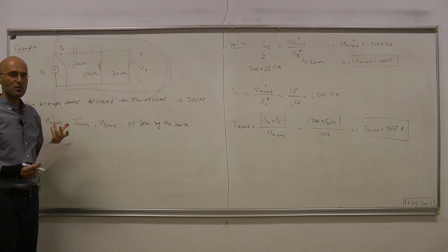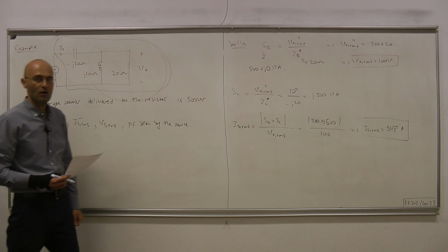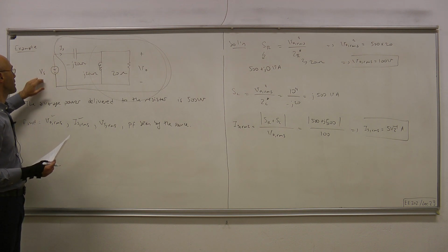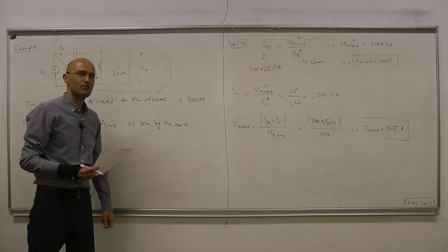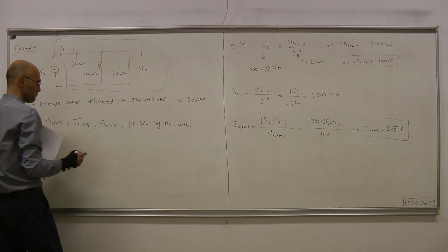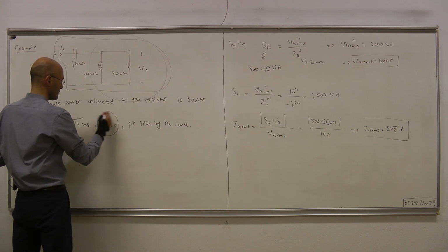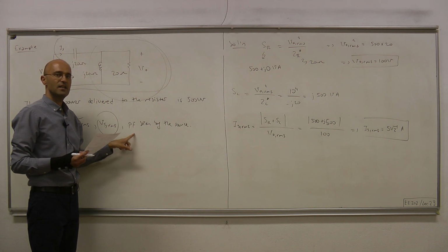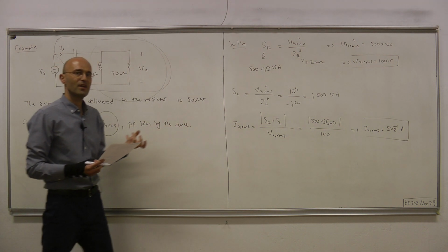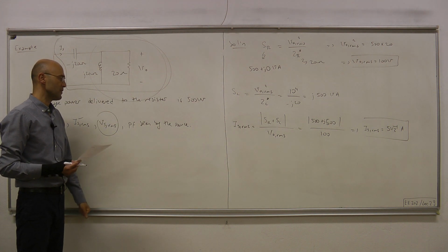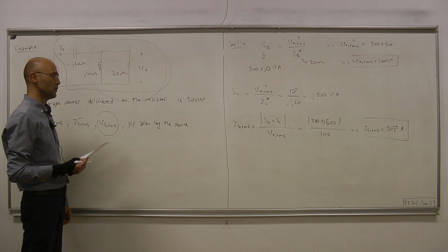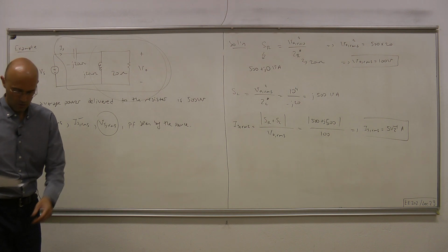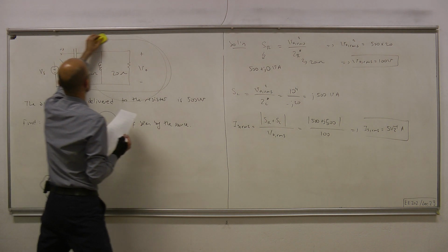Once that is known, its magnitude is known too, namely the apparent power delivered by the source, and then apparent power divided by the effective value of the source current will give us Vs RMS. Also, from the complex power information, we can easily obtain the power triangle, which will give us the power factor seen by the source. So let's complete this problem.